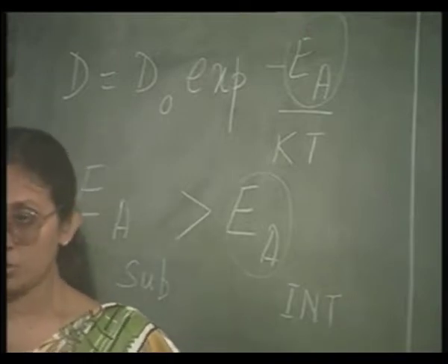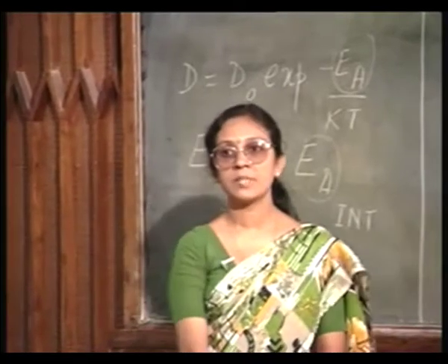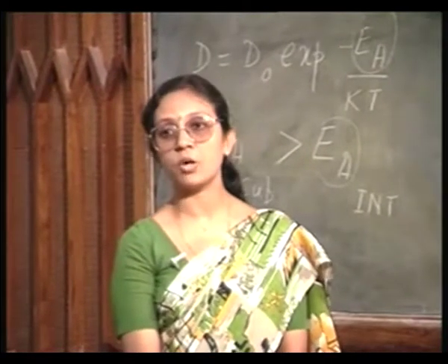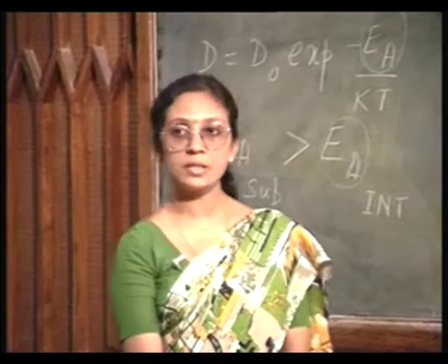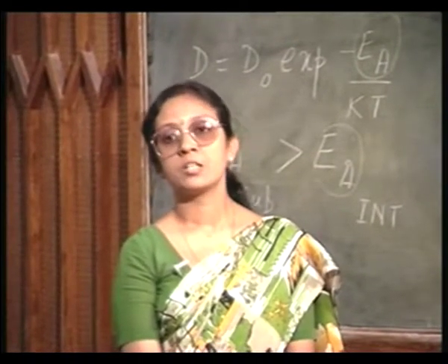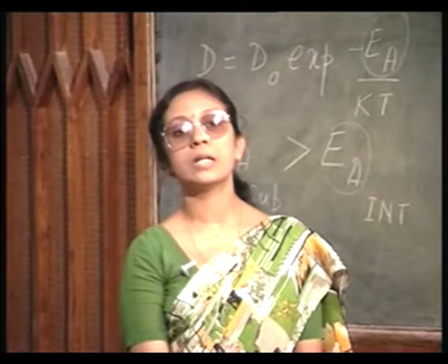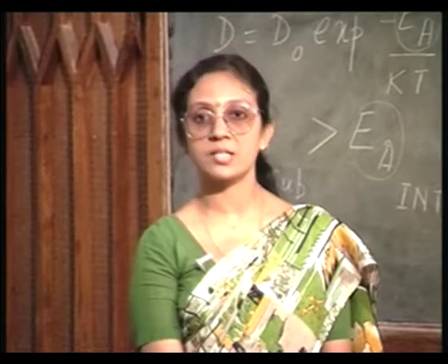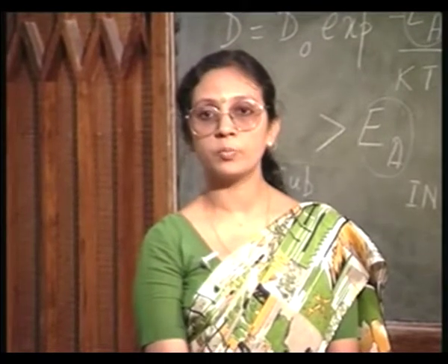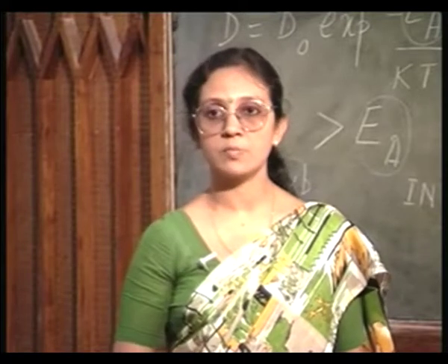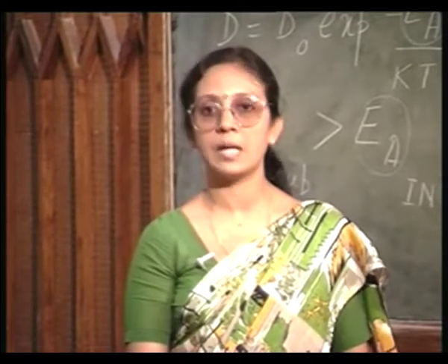So, what we have seen physically is now being given to you mathematically. This is the significance of this mathematical representation, that the diffusion coefficient for an interstitial dopant is much higher, that is the diffusion is much faster in case of a dopant which is interstitial. Physically, obviously you understand that that is because its movement is relatively unhampered.